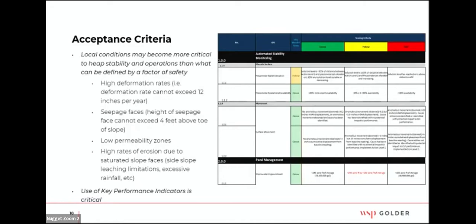So do you then say, you know what, I'm not going to accept more than a foot per day of pore pressure increase inside my heap? I'm going to then change either irrigation or something else that I'm going to manage on the heap to reduce that rate of rise, rather than waiting for you to exceed a safety factor, right?